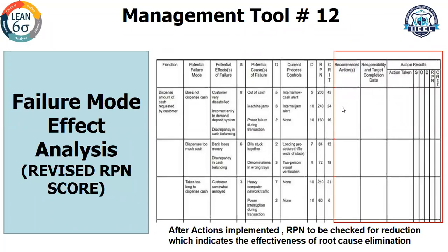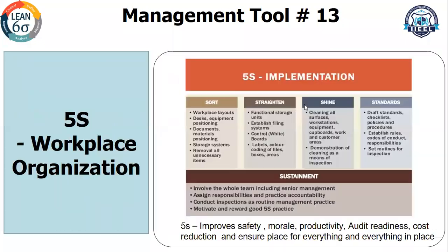And that's this. Many people don't use this tool. After every 3 months, you have to use this tool to check whether your RPN number has reduced from 200 to 50 or 20. So this tool is something you have to implement after taking actions, checking what is now causing the problem and how the RPN looks. It's a very, very important tool.